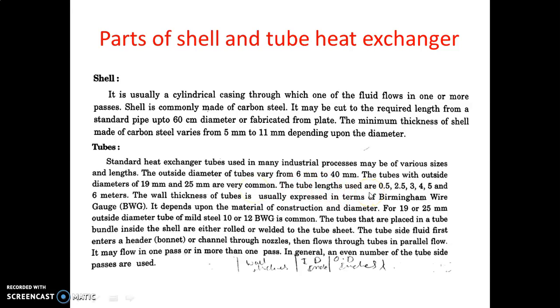The length of the tube is 0.5, 2.5, 3, 4, 5 or 6 meters, so depending upon your heat transfer load or calculation, you can take this length.